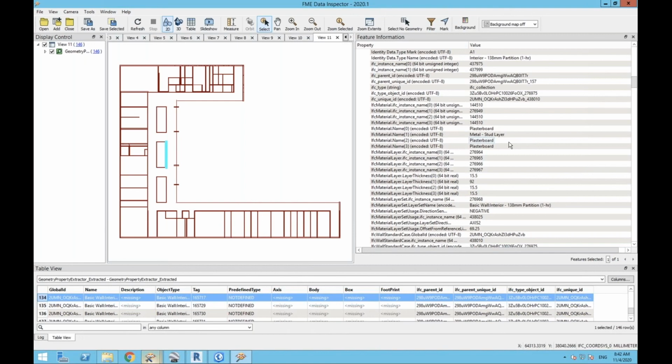And you know, RVTs are meant to go from Revit user to Revit user to Revit user, assuming they all have the same family files. So we need some way of figuring out how to get that information out, which we'll be working on going forward. Meanwhile, we know we can get it out through IFC. When Revit writes the IFC, it merges all that family information in.